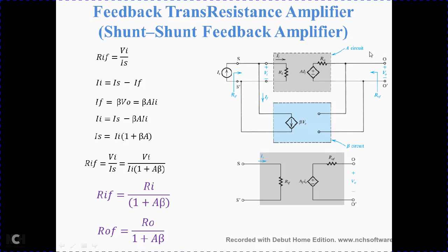The output circuit of this and the previous are the same, so I am not doing it again. You can try for different input and output resistances for different topologies in the same manner. So if any application demands both input and output impedances to be low for a given circuit, then one can go for a trans resistance amplifier.